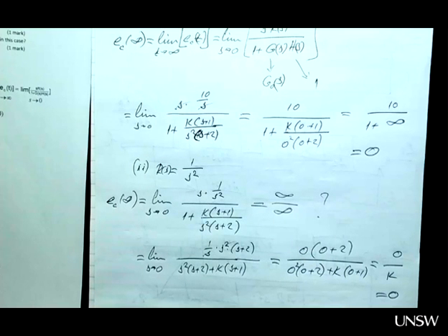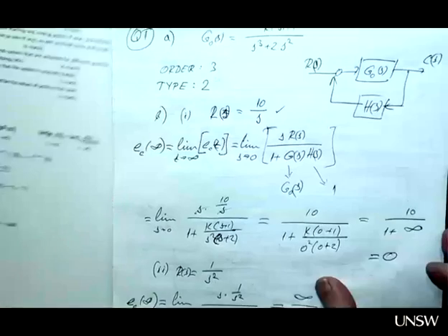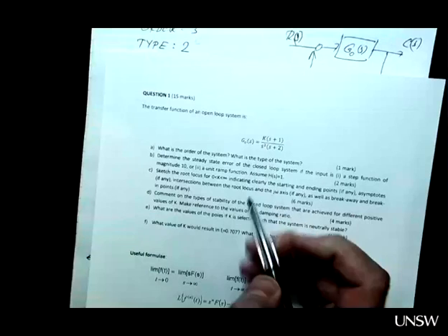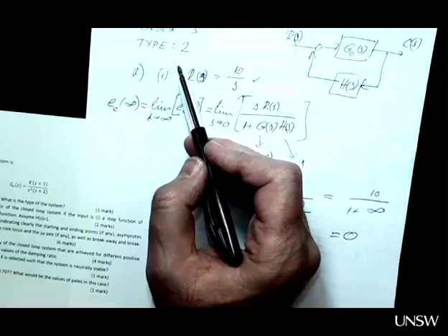So in both cases, we have a 0 steady state error. And if you remember lecture 10, we derived a table that no one expects you to remember, to memorize, okay? But in that table, we said the higher the type, the less the steady state error we are going to have. So we have a reasonably high type, type 2. So that's why we have 0 steady state errors.